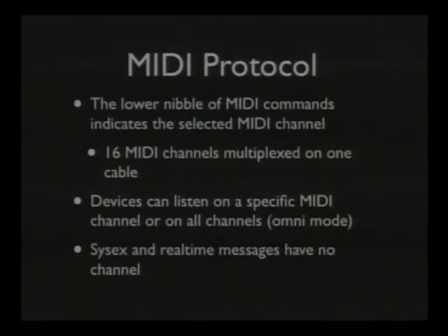On MIDI, you also have MIDI channels, which is another way to multiplex information on this one serial link. So you can have 16 MIDI channels on one cable, basically. So you can connect multiple synthesizers and address them individually. And the MIDI channel is always encoded in the lower nibble of the command byte. So devices can listen on a specific MIDI channel or on all channels. And there's this thing called system messages, which is further split into real-time messages and system exclusive messages, I think they're called, which is used to send system information which is not musical.